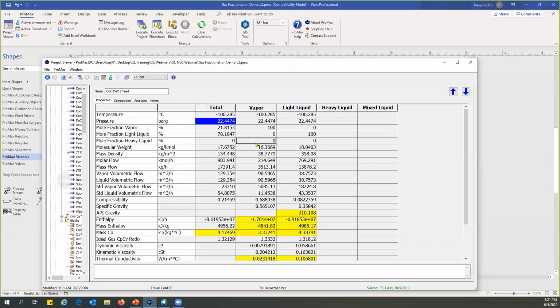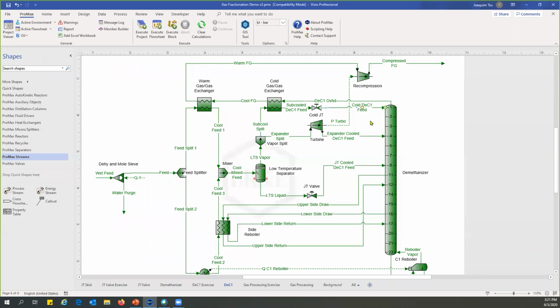Even then, it's really pushing it. Negative 30 to negative 25 is generally what you're looking at. But yeah, purely refrigeration without an expander, you can't get cold enough. It will be impractical. You have to use something like ethane as your refrigerant, which is not ideal. It's very expensive.